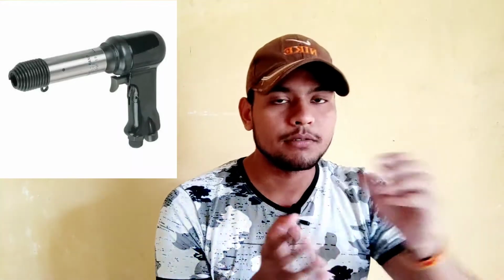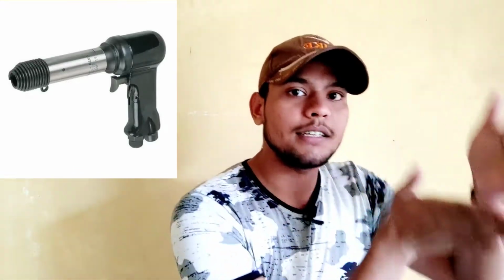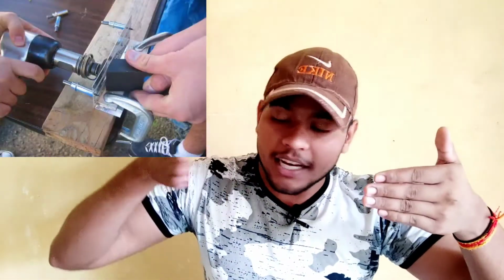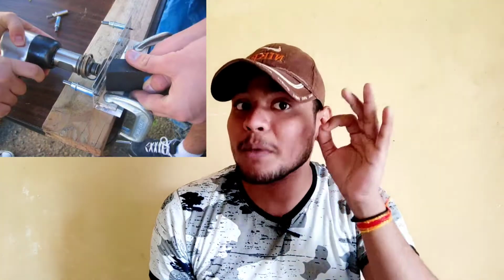They can be available in many types. They are like 1x, 2x, 3x, 4x. These simply imply their powers, meaning 1x is lesser than 2x, then 3x, then 4x, likewise. One more thing required when you are doing riveting by pneumatic power is that your rivet gun and your bucking bar should be at 90 degrees, so that your riveting can be perfect.